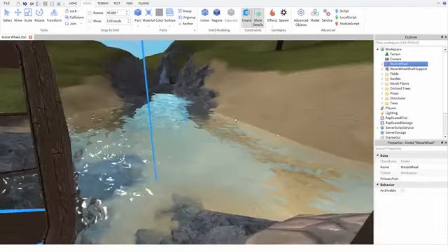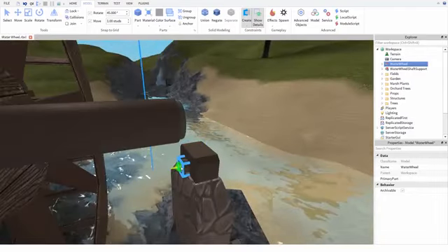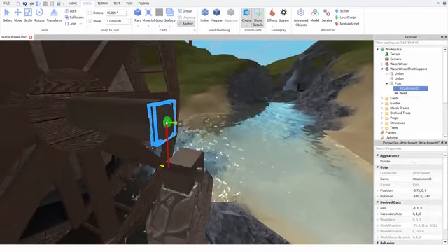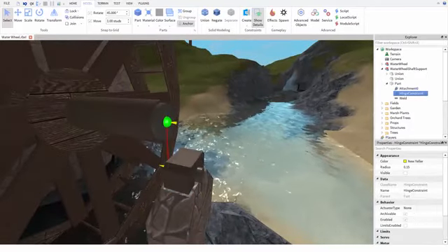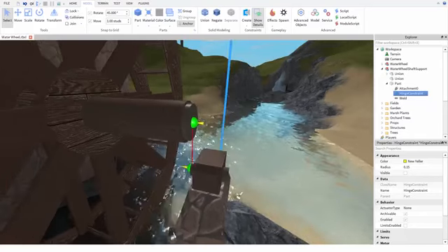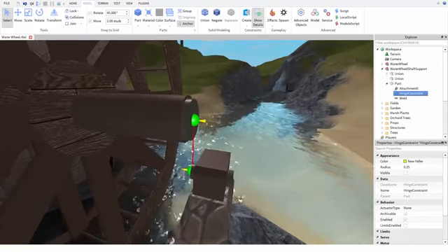Now we just have to click where we want the attachment points. In this case, I'll put one on the support over here and the other on the end of the shaft of this wheel. This here is enough to allow the wheel to spin, but there currently aren't any forces or torques to make it turn. What we can do is change this hinge to become an actuated hinge, which provides power to the joint and forces these attachments to move.